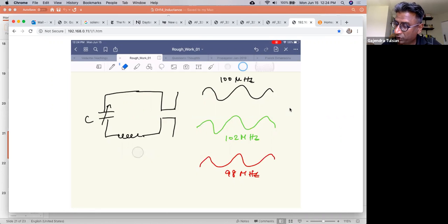And then what you do is you take another inductor and the signal is transferred. So you've picked up the signal from this tuning circuit, you transfer the signal via a transformer to another circuit, and then process that signal in this black box. So again, this is the catching device, and then you transfer the signal via transformer, or you couple it, and then here's the processing circuit.